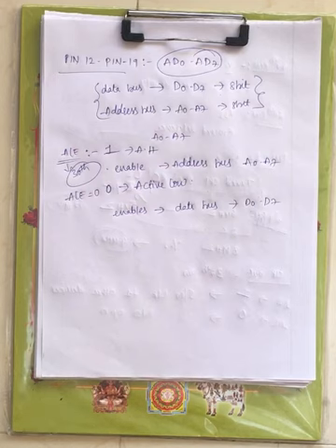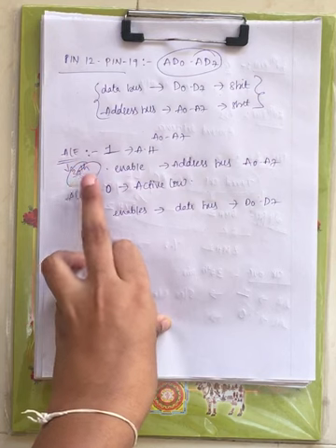AD0 to AD7 lines can't carry lower order address and 8-bit data at a time. Whether to carry lower order address or 8-bit data is decided by the address latch enable signal.